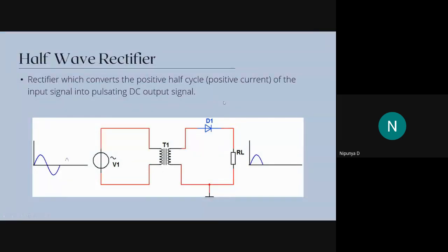And we know that rectifiers are of two types, half wave rectifier and full wave rectifier. Since I hope that most of you know the working of this, I will just be briefing you on how exactly that works. As the name suggests, a half wave rectifier just conducts half of the input cycle, so the output will have just 50% converted. How this works can be easily analyzed by knowing the working of the diode. For a diode, when the voltage on the p side is greater than the n side, it acts like a closed circuit, it is forward biased, because of which it entirely conducts. Whereas whenever the voltage on the p side is less than that on the n side, it acts like an open circuit, since it is reverse biased.